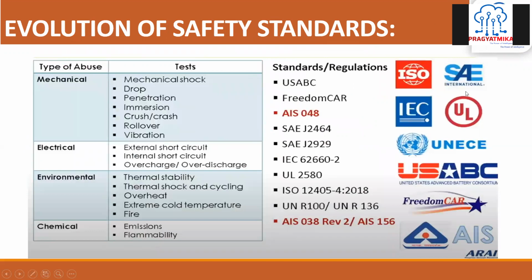So all of these standards are looking towards the mechanical, electrical, environmental, and chemical, these 4 types of abuses and the tests related to them, which again relate to the safety and the performance of the battery pack. Globally, these are the different standardizing bodies. And in context of India, it is the AIS 048 and AIS 038. Those are the 2 more important ones related to the battery pack.